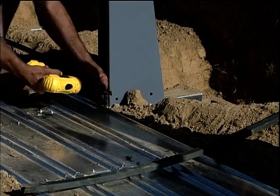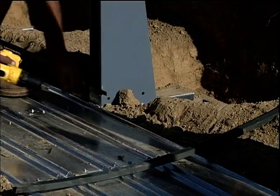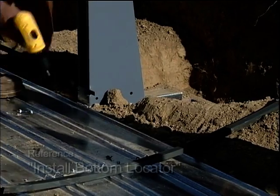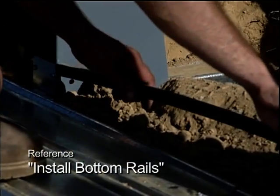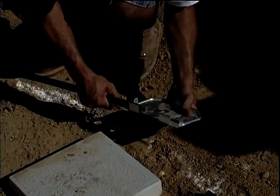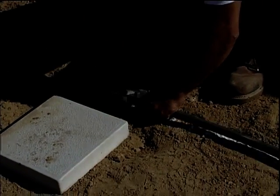They fit tightly between the side verticals and must be installed at this time. Be sure the bottom rail locator is mounted with the hook ends up and fastened to the side verticals using the top set of holes at the bottom of the side vertical. Please reference Install Bottom Locator and Install Bottom Rails. Continue the bottom rail installation by starting at the side vertical supports. Place the first circular end of a transition bottom rail into the bottom rail locator and the opposite end in the vertical end cap. Push the bottom rail to the stop of the plate.